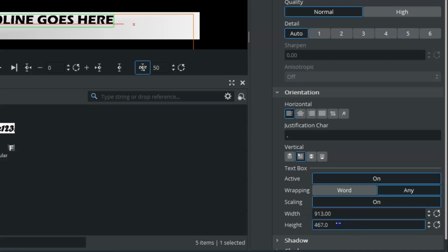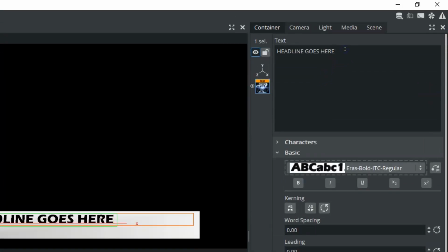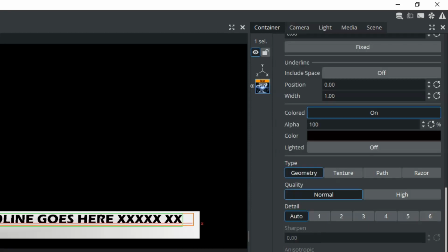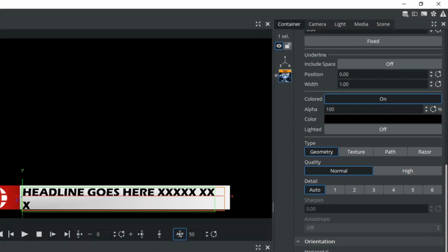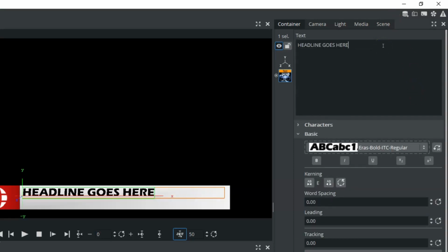We also want to place the height here, so as we adjust the height down, you'll see that orange bar adjust down. Now that means anytime you come up and type within your text editor here and you type extra spaces, it's going to wrap on that space and actually cut off. If we increase that height of the orange bar, it's going to continue on to the second line, but since we decrease the height and have it cut off, it's not going to show that second line. So we're going to go up and delete the extra text here, but know that it's all set up with our text constraint here.